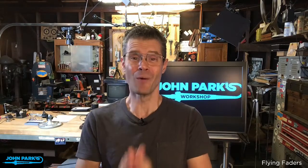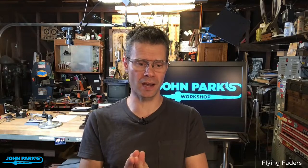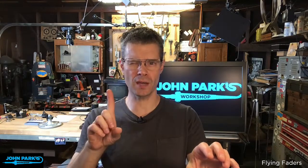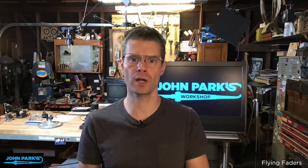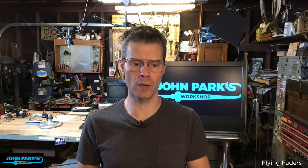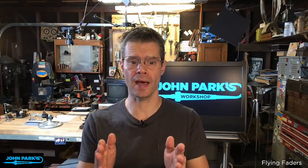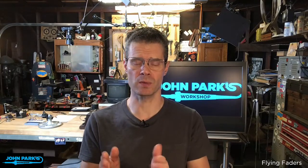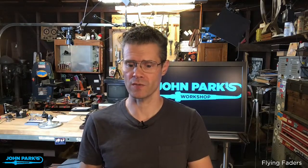I think you agreed to that. We're going to collaborate on it. I'm going to build the physical coffee scale with 2 load sensors, I think, for one application, maybe just one for another. Measure grounds or measure the shots pulled, and that's gonna be a really cool guide that'll show you how to use that load cell and that 24-bit ADC to get really precise measurements. As you saw there, it'll measure down to 0.1 gram, which is fantastic.